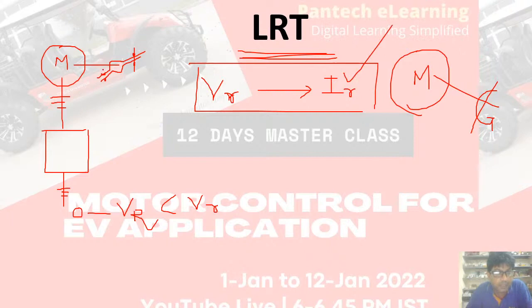But if I externally lock the rotor and apply the voltage, then with a voltage of V capital R, it will start to draw the rated current as it is shorted. So I have to find out that voltage.